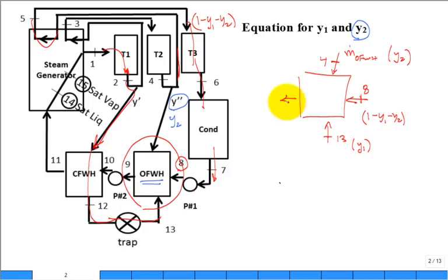And then what goes out? Well, you just do the balance, and what goes out goes through the second pump, goes through the tube side, that's back to 100%. So that's state 9 at 100%. The book sometimes uses this percent in parentheses, fraction or percent in parentheses, to indicate what fraction of what went through the first turbine is coming in each of those inlet streams. Does that notation make sense? So really the mass balance is all described by these terms right here.